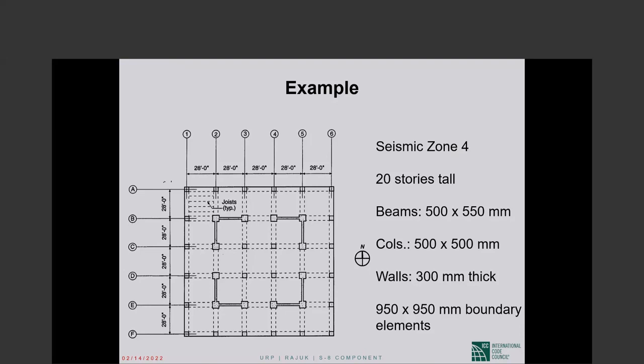So the coupled shear wall will take the place of an isolated shear wall in a building frame system. You can use it, but only in conjunction with 100% gravity force resisting moment frames.